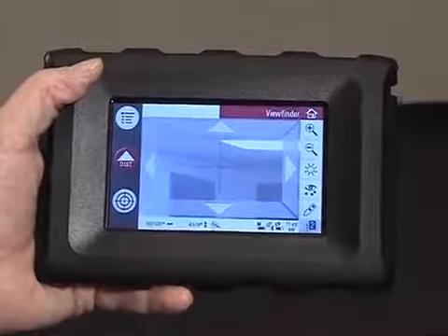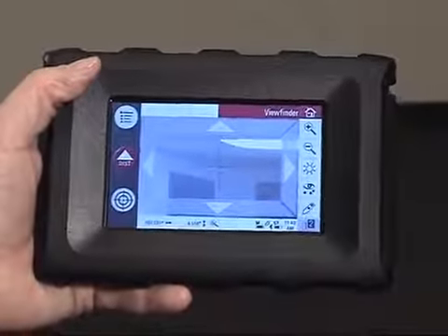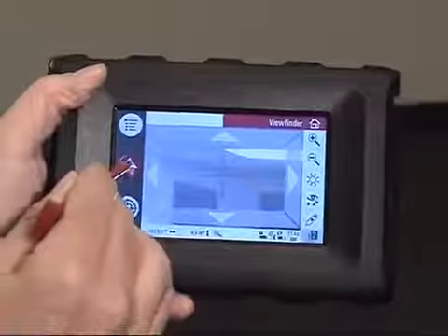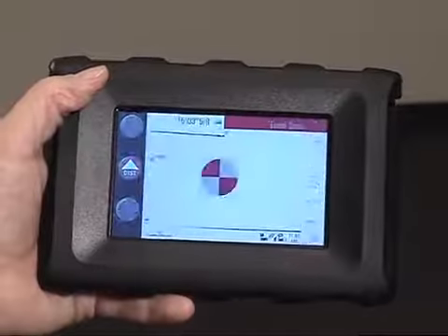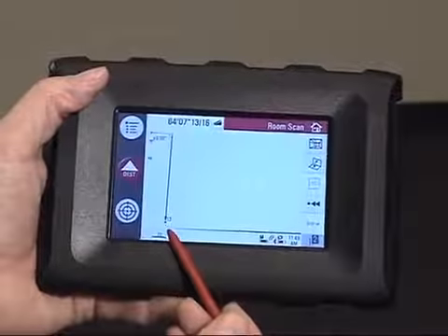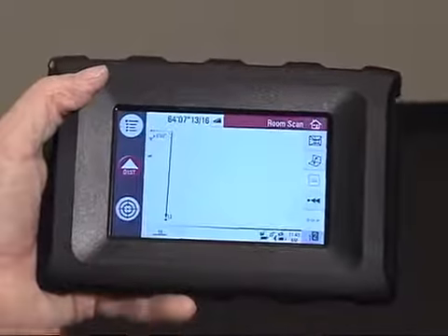I can also pick up and walk to that location to visually see where the red dot is in the corner of that location. But I know it's there. I'm going to hit dist. Now you can see we've located our new point, point 13, which extended from point 3 down the new wall segment.